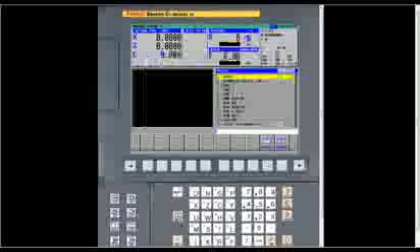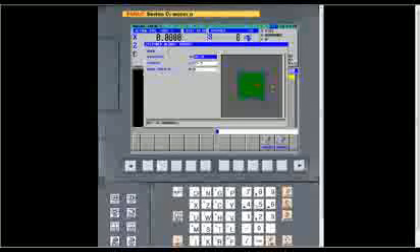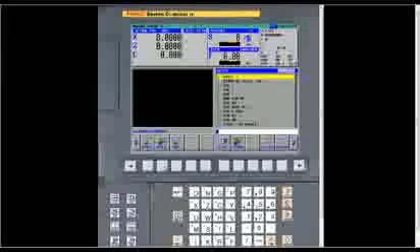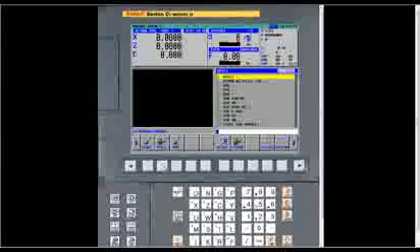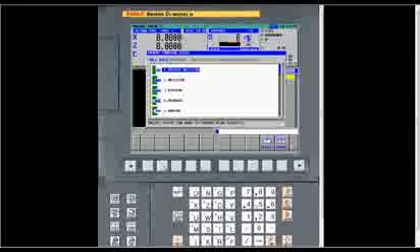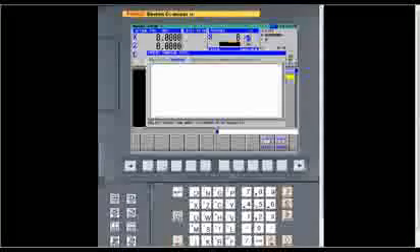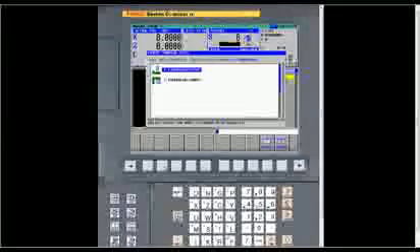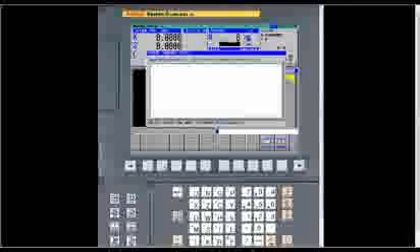If you select the blank, it asks for a diameter, a length, and a work origin in Z. Very simple. And then cancel out of that. Now we're going to go into a brief overview of the different cycles in the turning mode. We go into cycle, and we've got 5 different selections here on the software the way I've got it set up: hole machining, turning, residual machining, turn grooving, and threading. Those are your 5 different selections for turning.